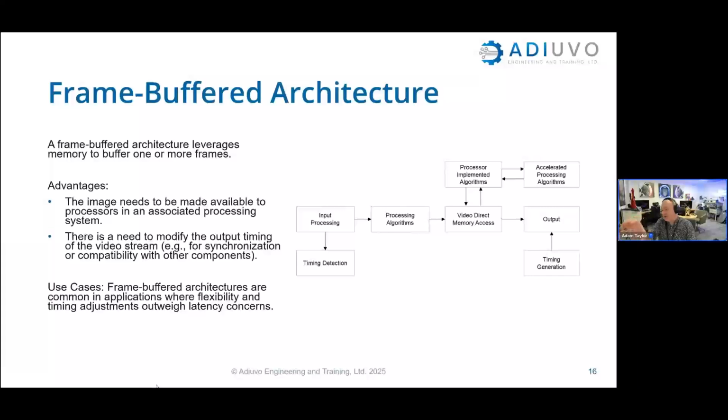That's where, if you're doing any Video for Linux, the processor might pick it up and begin to use it. Having this means that we can manipulate the image in the processor, in the soft processing world. If you're doing, for example, CNNs or image-based processing, this is quite important, because you've got to get the image into some sort of memory mapped space.